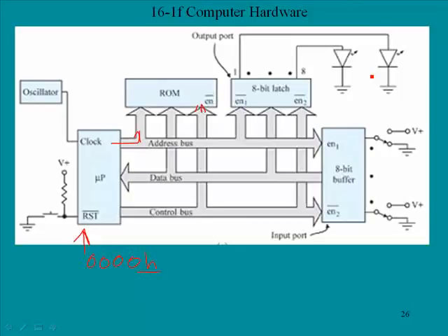Okay, since our first instruction was IN, the instruction register now contains 11011011, or DB in hex. Upon decoding the instruction, the microprocessor learns that it is an input instruction. So the instruction that's being given is that we're going to input data.